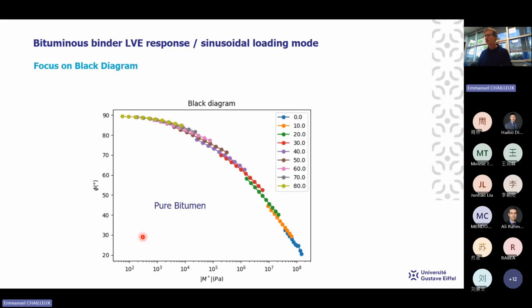And in between, we have a continuous behavior. We are going slowly from elastic behavior to Newtonian fluid, with a continuity of isotherms, which is due to the molecular structure of bitumen, which is composed of different molecular sizes, representing a continuous distribution. It is very important.